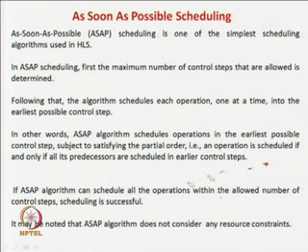So even if you take the as early as possible condition, here we actually decide what is the maximum number of time steps allowed. Then we schedule as early as possible, but all the operations cannot be done in time step 1 because of the dependency. Still maintaining the dependency, you have to find out what we can do as soon as possible. So in this case, you can think that we will be able to minimize our time requirement. So that is basically one kind of a schedule.